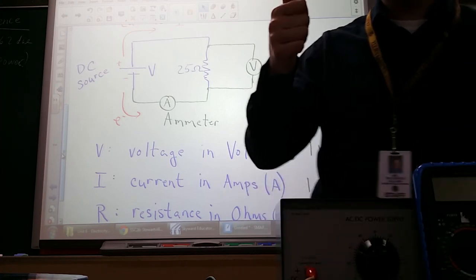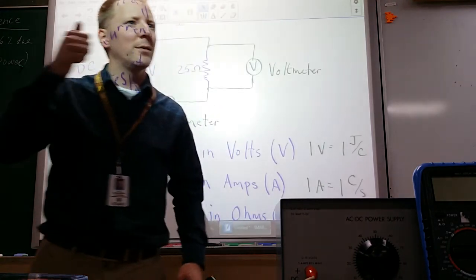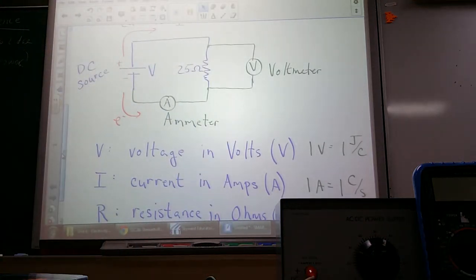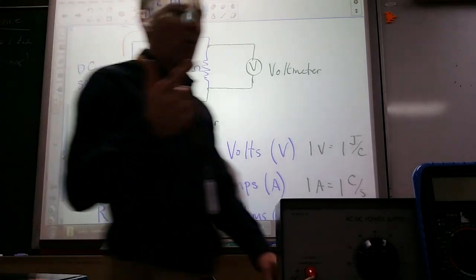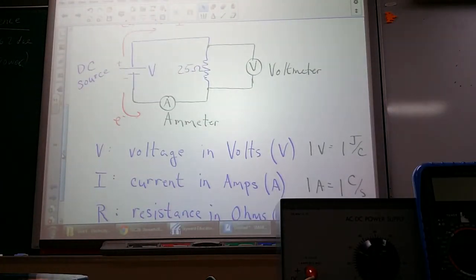And then the first experiment is just to increase the voltage, which you can read on your voltmeter, from I think 1.5 up to 9. Measure and keep the same resistance in each time, record voltage and current. Second one is pick one, and I forget what it says, but try only replacing the resistor value then. So you'll pick different ones.